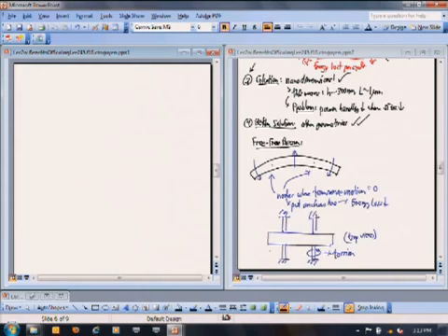Okay? But there's nothing like this, where you basically say, okay, I have anchor radiation. That is a substrate loss mechanism. Just eliminate the anchor radiation by eliminating the anchors. Right? The fact in mechanics you have so much design flexibility, you can do that. The other solution to this,